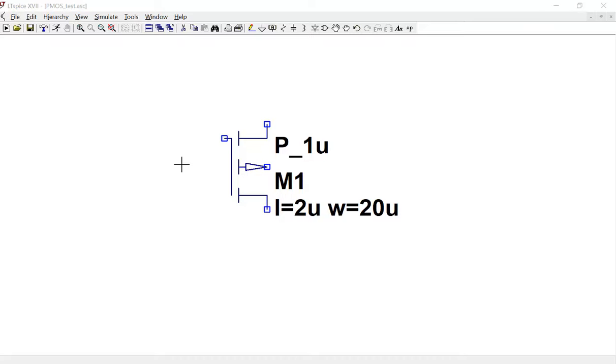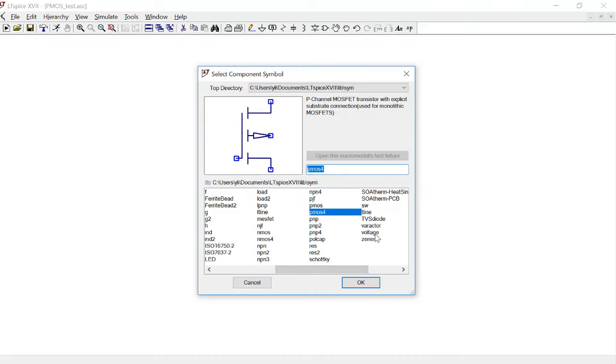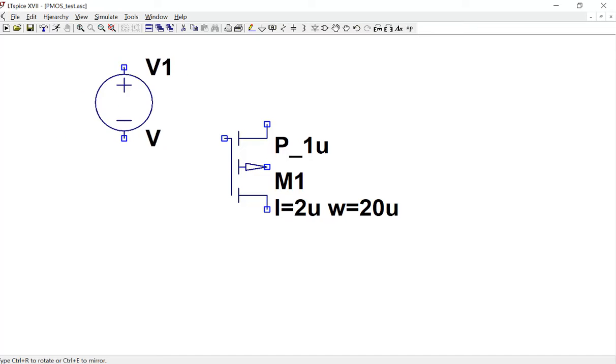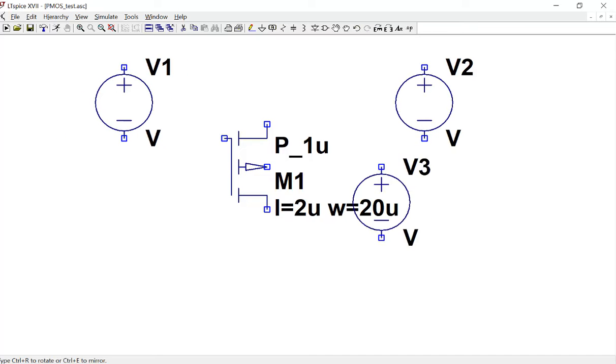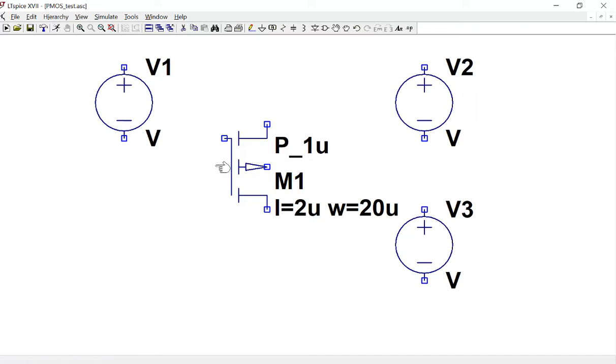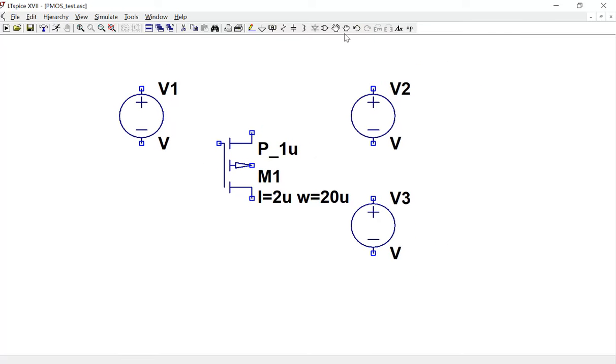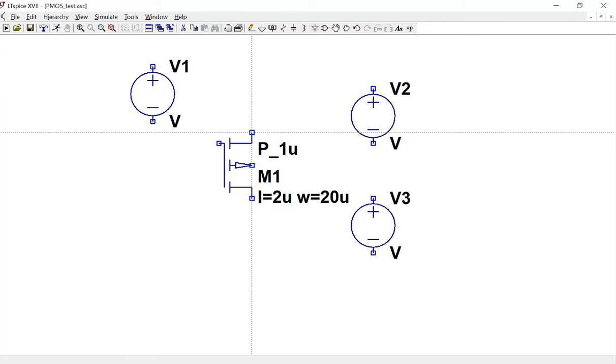And then let's grab a voltage. How many voltages do we need? Probably need a 3, since we need a body effect voltage as well. And then remember, it's a VSG. In PMOS, keep in mind, you need a VSG to turn on that transistor. So that's why I'm gonna draw a voltage drop from S to G, right?